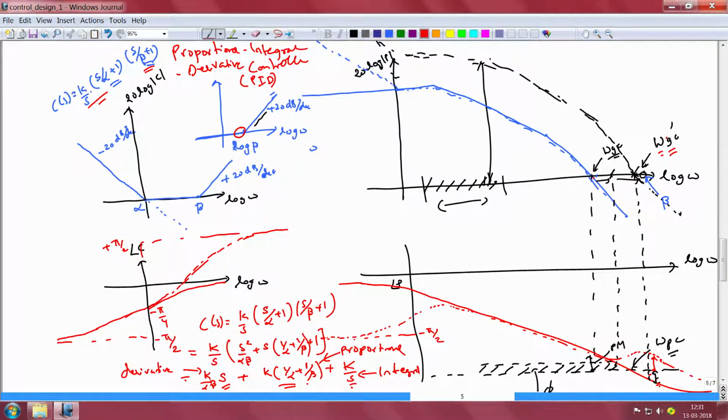The integral term allows us to achieve high gains in the low frequency range, or the frequency range where the plant's dynamics have not kicked in yet, and therefore enables us to track references and reject disturbances very well in that frequency range. The proportional term allows us to achieve reasonably good performance in the mid frequency range, or in the frequency range where you have the plant's dynamics being apparent, but still the frequencies are much less than the gain crossover frequency of the open loop system.